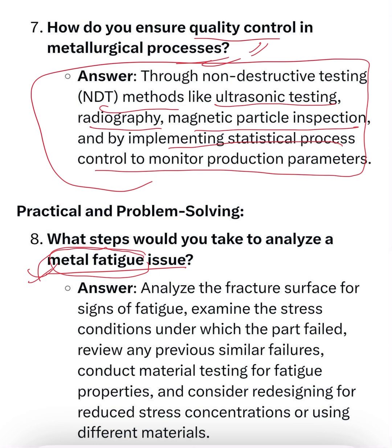The answer for this question will be: analyze the fracture surface for signs of fatigue. First of all, you can examine the stress condition under which the part failed. If you are doing fatigue testing, you have to apply some stress condition, like a stress amplitude, which is below the yield strength of the material. Then you see how many cycles it goes through before it fails, and then you can examine the fracture surface.